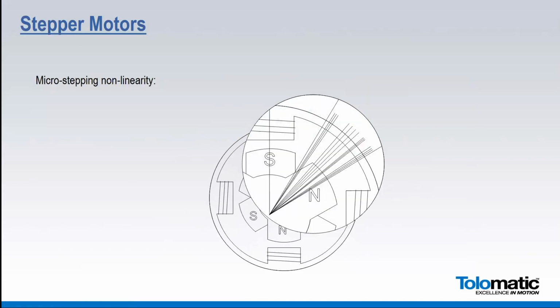The other thing to be familiar with if you're using stepper motors with micro-stepping is that micro-stepping is not linear. So you can't treat it like a high-resolution encoder. The micro-steps are not necessarily evenly spaced out. So if you do need high resolution, you're usually better off to go with a servo motor with a higher resolution encoder.